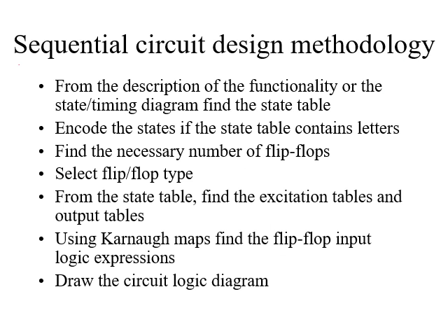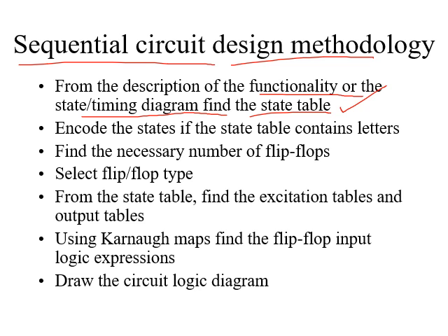Now let us see how we can design a sequential circuit. What are the steps followed? From the description of the functionality, the state or timing diagram, first of all, we design the state table. State table is defined. We encode the states of the state table which contains letters. We can encode them like 10 is A, 01 is B, and so on. Then we find the number of flip-flops required. We choose a type of flip-flop.